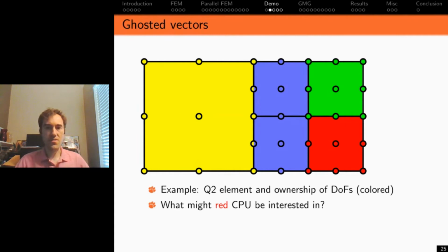And these circles denote the support points of these. When you construct finite element spaces, you often do a nodal basis where the finite element shape functions are 1 inside a support point and they're 0 in the other support points. And you can think of it this way. If you imagine the red cell here, I have 9 different shape functions that are quadratic functions, and they are, for example, 1 in the bottom left red, and then 0 in all the other nodes, et cetera.